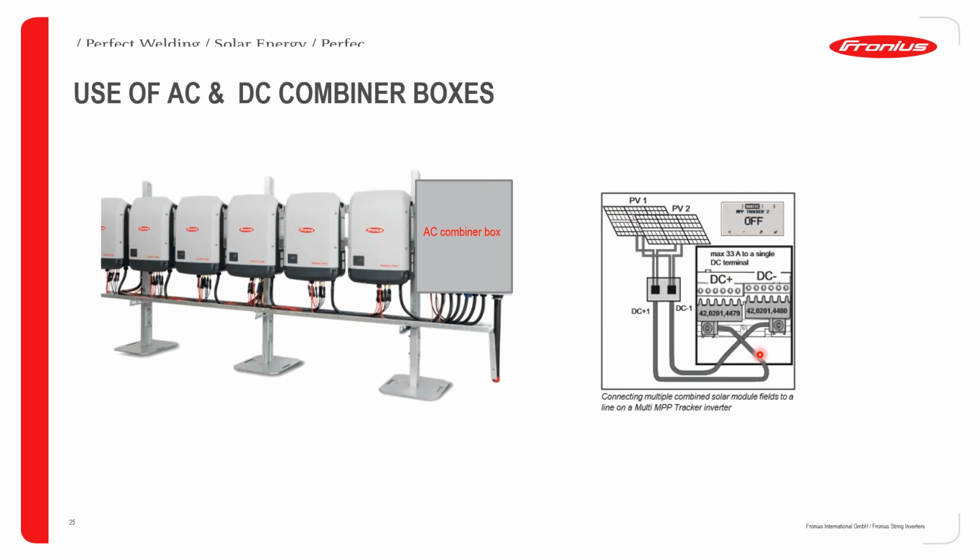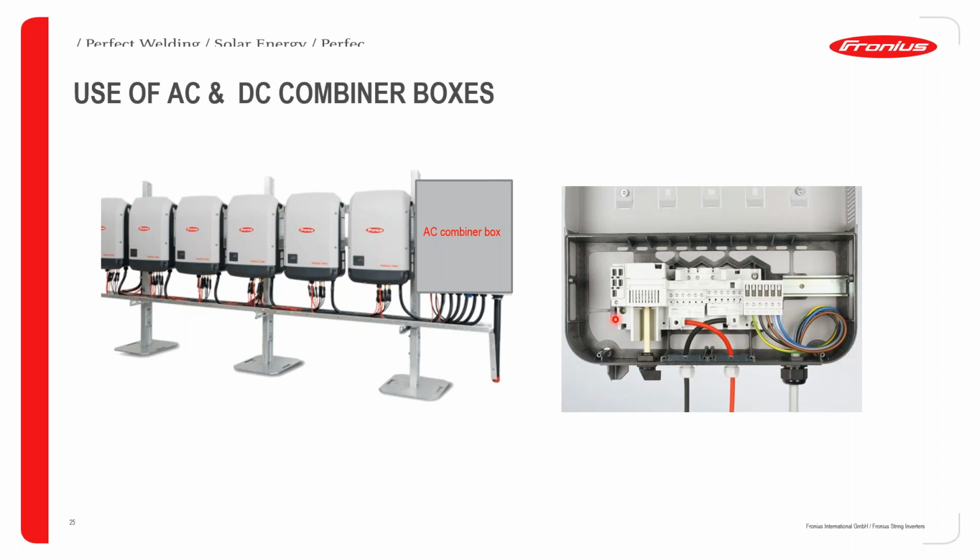On the right-hand side, I'm basically showing you what happens when we use the DC connector kit from Fronius. You only use the DC connector kit from Fronius if you are using a DC combiner box. So if you're using a DC combiner box, you need to use this DC connection kit from Fronius. And as you can see, they plug into the DC plus points and DC minus points. This is how the DC disconnectors actually look physically installed in a Fronius inverter.